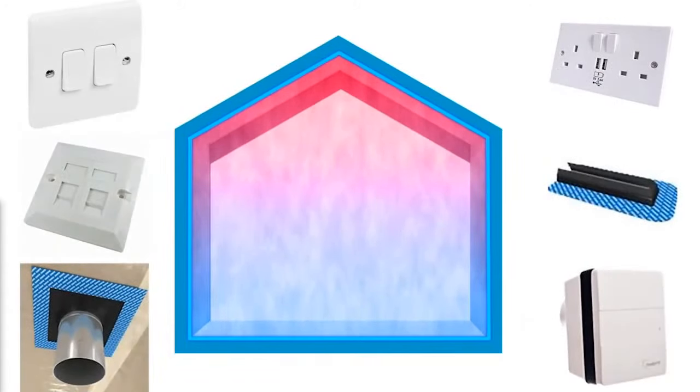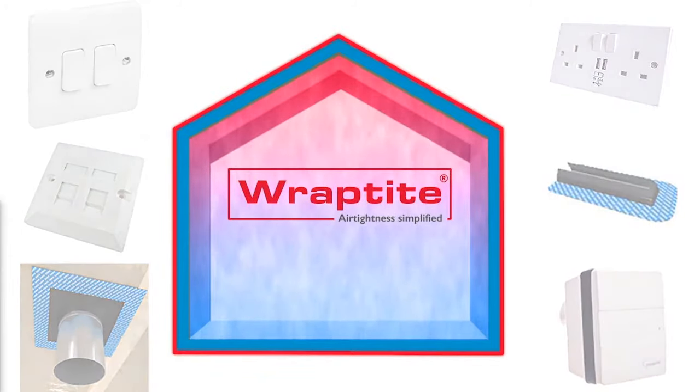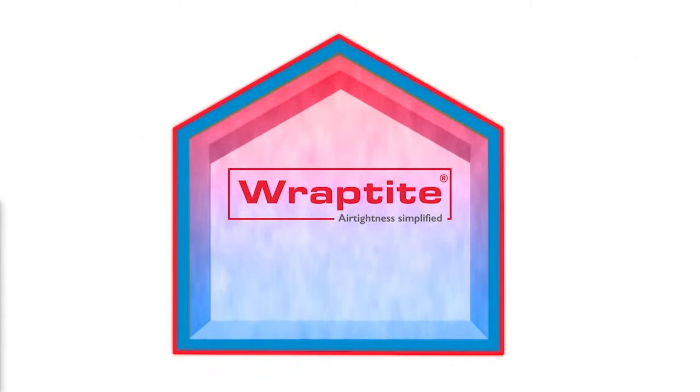This positioning requires the air barrier to be sealed at all surface and structural penetrations and remain sealed. If the membrane is damaged either during installation or by following trades or later refurbishments, for example, then both air leakage and moisture vapour ingress problems can arise. By moving the air barrier to the outside of the building, external systems such as our wrap-tight allow for an almost penetration-free airtight layer, which can be installed faster and more robustly.